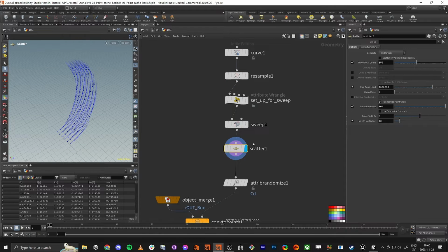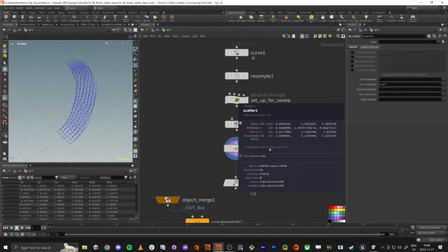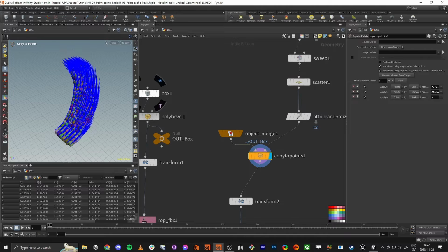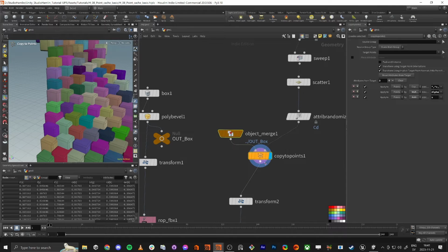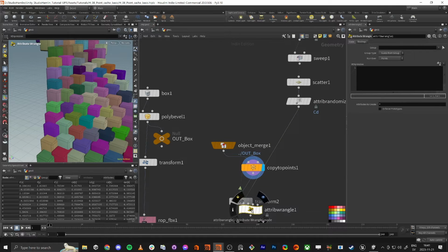It will go down here and it will also be scattered. So the scatter will copy point attributes. Star is all the attributes. So it will just copy the tan as well. And we still don't have it as we want it, but that's okay, because if we do a wrangler here, we can name this one fix rotation.